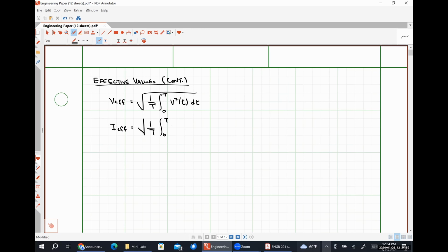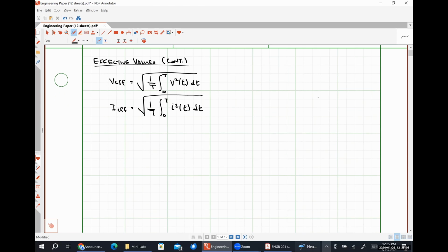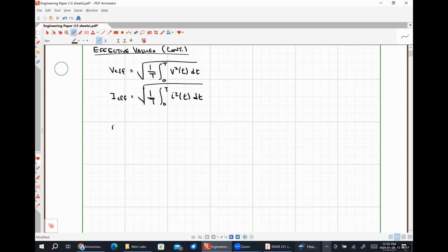Then we worked an example in which we found the effective value of a series of rectangular pulses with a duty cycle X that was between 0% and 100%. Now we're going to find the effective value of a sinusoidal waveform. So once again, it doesn't matter whether or not it's a current or voltage. I'm just going to arbitrarily say that I have some current i of t of the form I_m cosine omega t plus theta_I amperes.